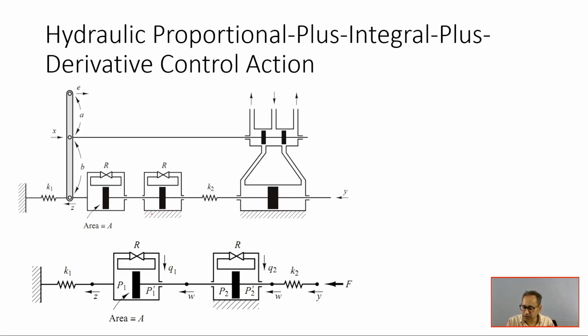See here, this is actually the PD portion, where this power cylinder as well as this dashpot are mounted to the ground, fixed to the ground, whereas this is floating. So, in this particular arrangement we have combined both the designs of proportional derivative as well as proportional integral controller, which we have discussed separately just now. You see here, these two dashpots are connected back to back.